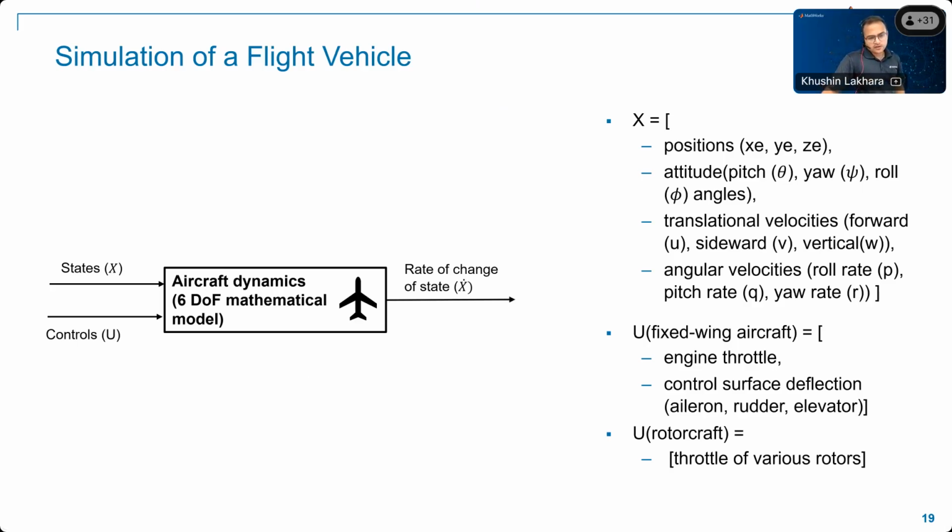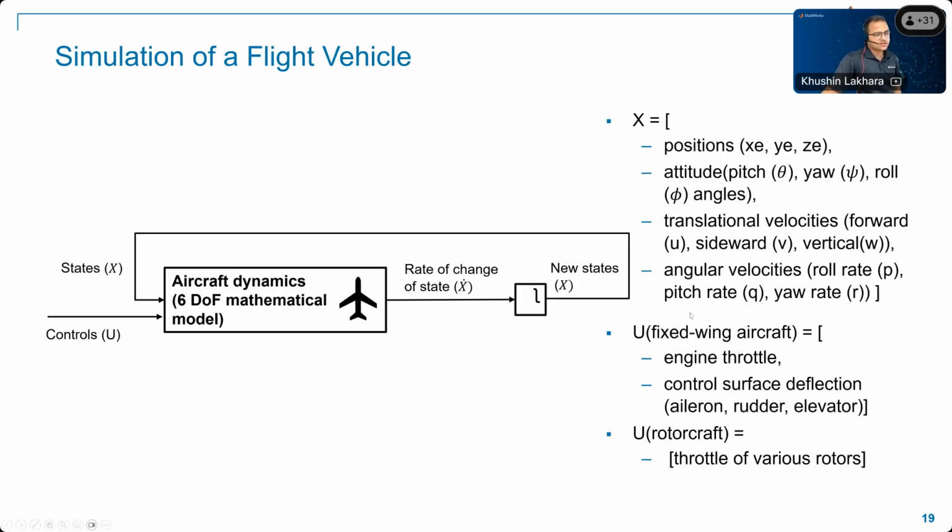So if we have the rate of change available and initial states are available, we can integrate and calculate new states. So now if you are giving the feedback of the new states into the similar aircraft dynamics, you can actually see how your vehicle will behave over time. And that's the basic philosophy of simulation.